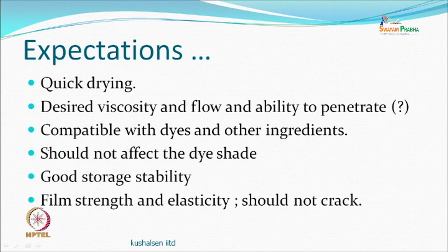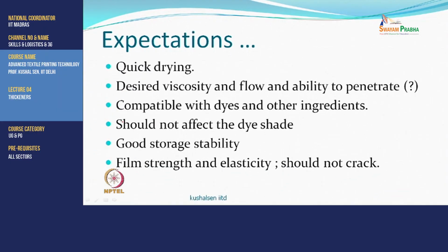Then after so-called printing and drying, the film should not crack. If the glass transition temperature of this polymer is high, then it becomes more rigid, and then during the folding processes, before you have fixed, it can develop cracks, and if the cracks develop, then the penetration, diffusion, etc., those portions will be affected and you may see some change.